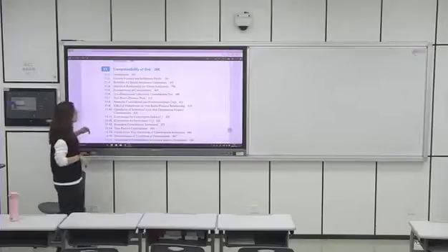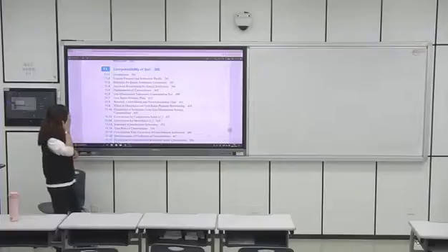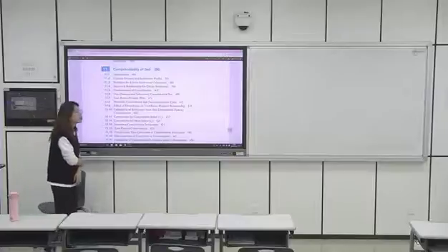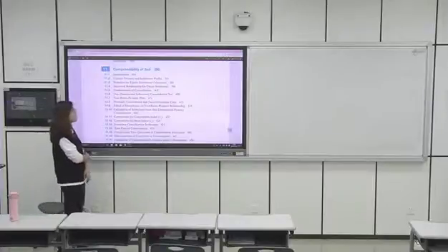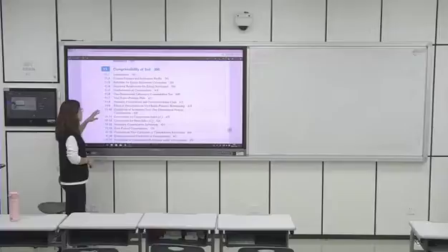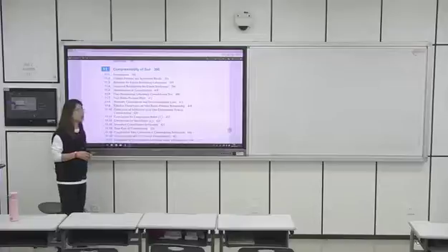And then we learned how to study the consolidation of soil. We use the one-dimension laboratory consolidation test. We explained the process of the consolidation test. And the main thing here is a void ratio pressure plot. That is the result we can obtain from a consolidation test.